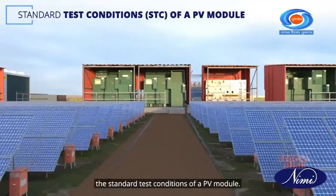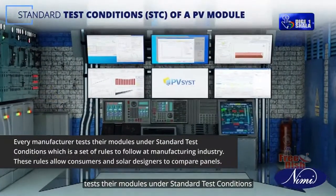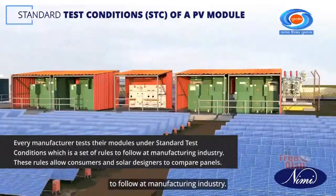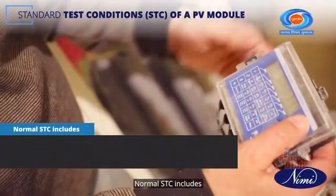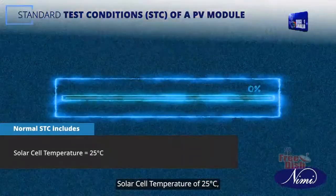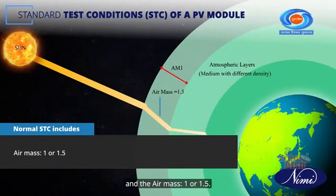Let us learn about the standard test conditions of a PV module. Every manufacturer tests their modules under standard test conditions, which is a set of rules to follow in the manufacturing industry. These rules allow consumers and solar designers to compare panels. Normal STC includes a solar cell temperature of 25 degrees Celsius, solar irradiance of 1000 watts per square meter, and an air mass of 1 or 1.5.